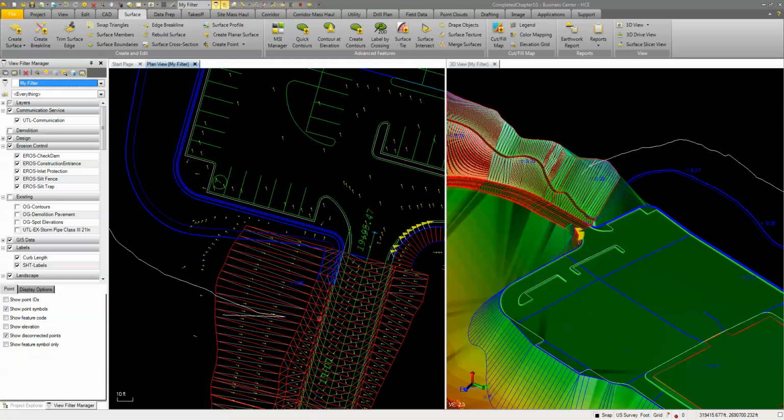Now we're going to delete this and break this off in a minute, but what we want to do next is pull back the corridor in this section, right? Because now we know that with this projection here, right about in here is the intersection of this. So I don't want to explode my corridor. I just want to move and remove this section of the corridor back to here, and I'll do some cleanup, and we'll show you that in the next video.